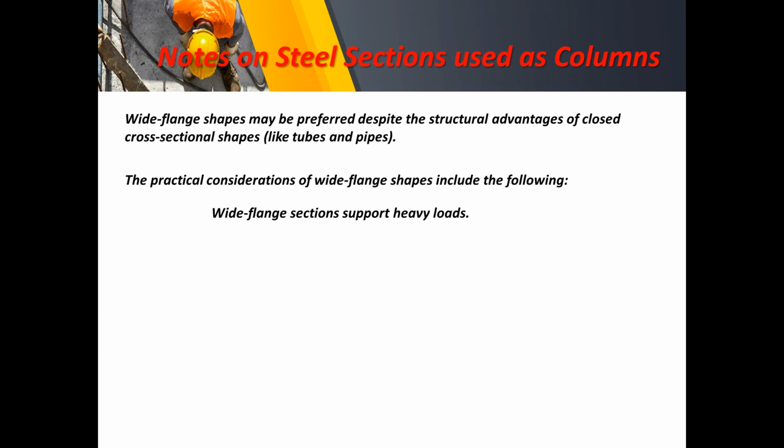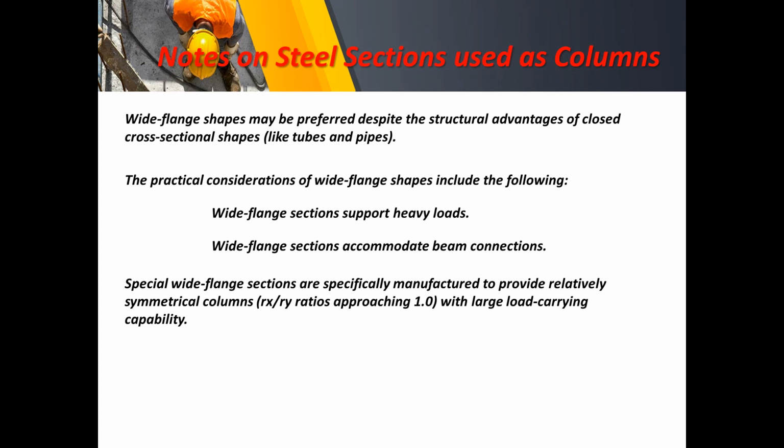Note that tubes and pipes are only recommended for light to moderate loading. Wide flange sections also accommodate beam connections because of their configuration.